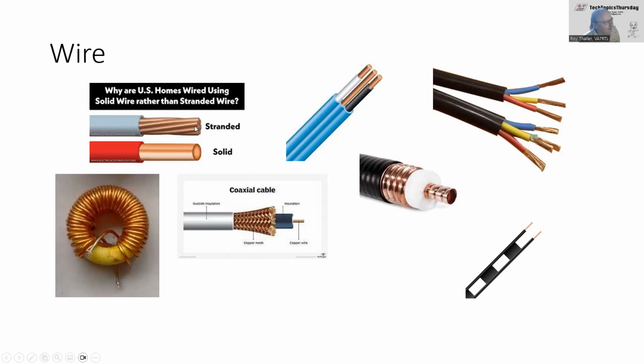And then also when you solder this, the solder tends to run inside the cable and can cause it to act more like a solid piece and might break off here. And when you strip off the wire, you may break some of these strands, or when you stick this into one of these terminal strips, some of the strands may not go into the hole, so there are little ferrules you can put on top of it to help you make those connections.